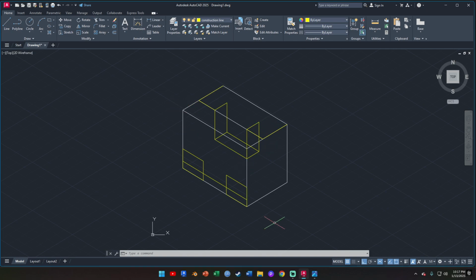So what I was saying just now, right, with the outline, if you switch to the outline on your property here, your layers, what you would want to do is turn on line weight. So line weight is this symbol here, right? You click on that to turn it on, and I can basically draw what would be shown, right? What wouldn't be hidden. So we know that this would be shown, this, this, this,